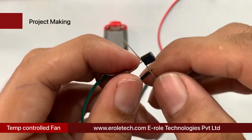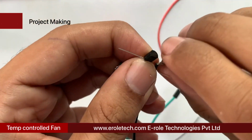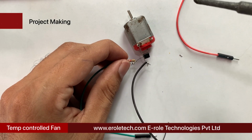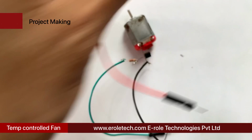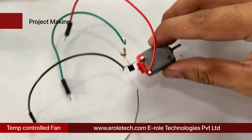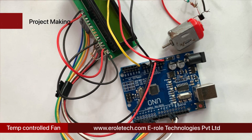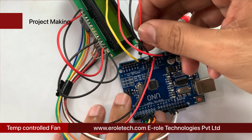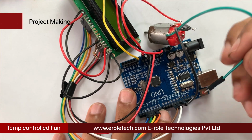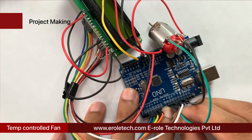Now connect a black wire at its emitter terminal. Now we will connect one end of the DC motor with the collector end of the transistor. Now connect a red wire with the second end of the DC motor. Now connect the red wire of the motor with the V-in pin, the black wire of the transistor with the ground pin, and the green wire of the transistor with pin number 9 of Arduino.